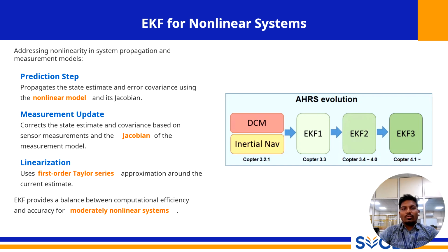This allows the powerful mathematics of the original Kalman filter to be applied. The filter provides a balance between computational efficiency and accuracy for moderately nonlinear systems. It may not be as precise as more advanced filters, but it is highly efficient, making it perfect for the embedded processor on MAVs.